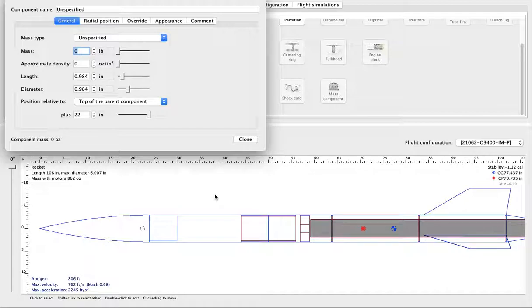So you may even need to throw in something like some weights. And this is a common practice. People put a lot of weight in the nose cone. And if you ever wondered why you always had to make the front of your paper planes extra creased to increase the weight, and add a certain weight to your nose cones, if you've been doing this a while, this is why. You need to get that CG above that CP for a stable flight. So we can go ahead and say, all right, we have a heavy eBay at 10 pounds. Okay, things are looking a little bit better.